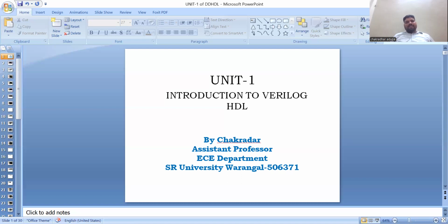For example, the size is written in decimal and specifies the number of bits in that number. The legal base formats are D for decimal, H for hexadecimal, B for binary, and O for octal. The number is specified in consecutive digits from 0 to 9, and A, B, C, D, E, F for hexadecimal numbers. Only a subset of these digits is legal for a particular base. Uppercase letters are legal for number specifications.